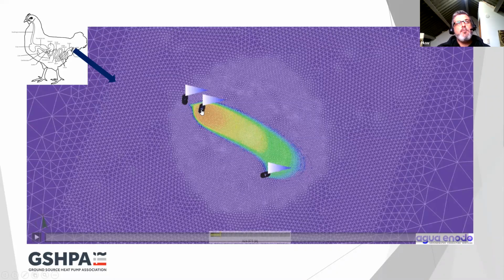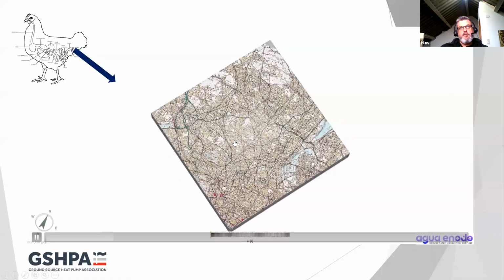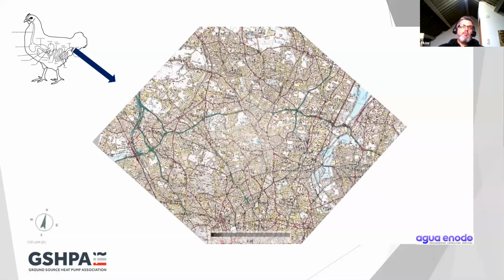We have the injection borehole, which is down gradient of the abstraction borehole. We can see the impact of a cooling dominant system, so we're dumping warmer water into the aquifer. This is moving away from our pump and dump system, and it forms this plume, as we've seen in some of the other slides earlier. And this is an evolution of the plume over time.